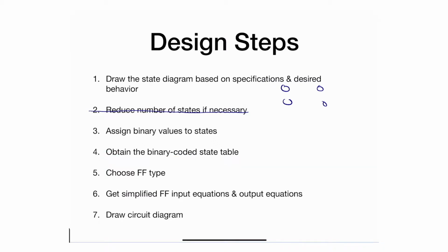If you were paying attention, we're moving in the complete opposite direction from the analysis. Now we're going to go to the table with the next state, the inputs, the present state, and a bunch of outputs, and you figure out the Xs and inputs and a bunch of zeros. So you write the state table. And then you choose a flip-flop type.